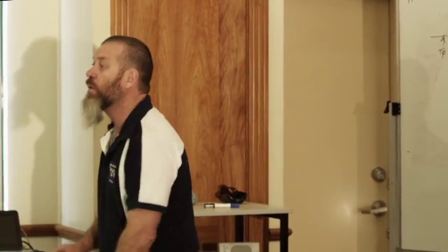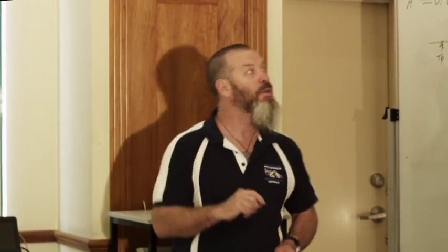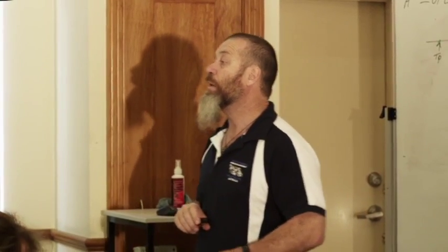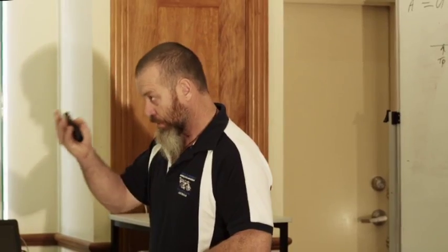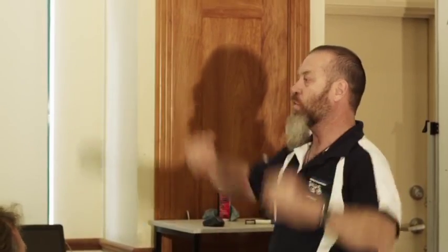Now this is an example of a truss connection. Question: is a truss top plate an outside wall connection? Yeah? Which formula do I use? Exactly. DBC divided by 2 plus overhang. The truss is sitting on that wall and sitting on that wall. That's about 10 metres. Half of that is 5 metres plus the overhang. That's how I come up with it. 600 was the spacing in the connections. Half of 600 plus half of 600 is 600. 5.6 times 0.6. That's as simple as it gets.